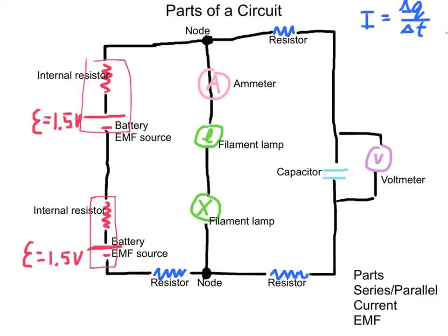This is a voltmeter. It measures the electrical potential difference, or the voltage drop, or the voltage across something. Notice this is in parallel. Think two parallel lines, capacitor, voltmeter. So the voltmeter is telling me the voltage, V, of this capacitor placed in parallel. Ammeter in series. Notice it's in the line. I really should have broken the wire up there.